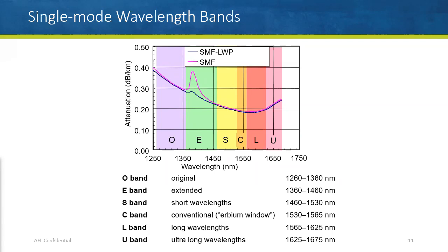In the industrial space, we typically use a dedicated fiber to transfer data one direction and then transfer data the other direction. We use dedicated fibers for that, a transmit and a receive, basically two fibers. And in the telecom space, they typically will use one fiber and send a different wavelength of light each direction. In some cases, they'll send multiple wavelengths of light down each direction, allowing you to basically do a multiplexing of multiple different pieces of light running down the same fiber in one direction and multiple coming back.